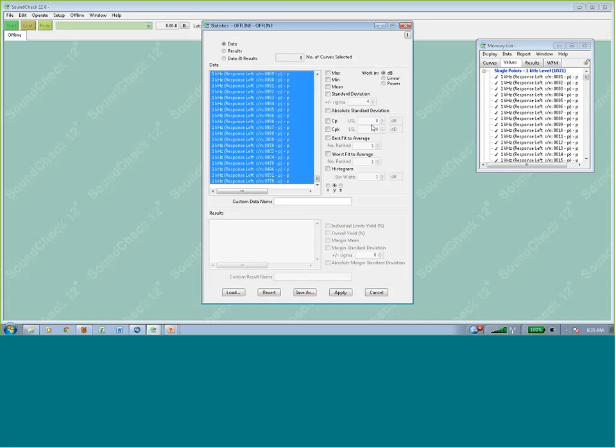Now over on the right-hand side, you see I have a new option down here at the bottom called histogram. There's also an axis selection, and this axis selection applies to all of these functions that you can see within this little box. When I choose the histogram, I can choose which of my axes I want it to run on. Now with 1 kilohertz sensitivity, magnitude is really the only one that makes any sense. But for example, if you were doing a bunch of loudspeaker measurements and were calculating resonance, with resonance you have the frequency, the magnitude, and the Q on your 3 different axes, and you may want to run a histogram on all 3. So you have the option here to choose which one to use.